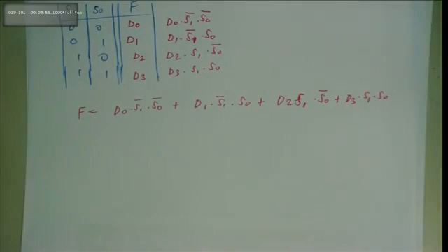Now if somebody were to ask you to build a multiplexer for 16 data inputs, straight away you'll know: how many outputs in this multiplexer? 16 inputs, therefore how many outputs? Will always be 1. There's no calculation. How many selectors? 4 selectors, right? But if we were to do this the traditional way, which is what we learned early on, what would be the result? It would be 64 lines on your truth table.